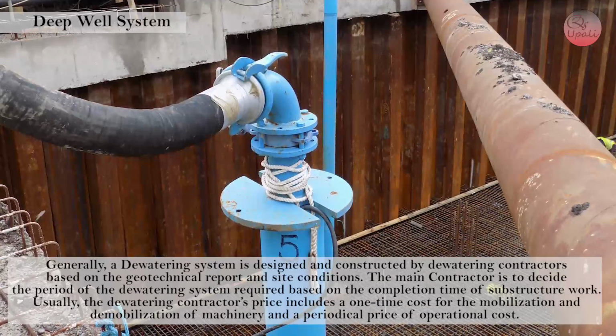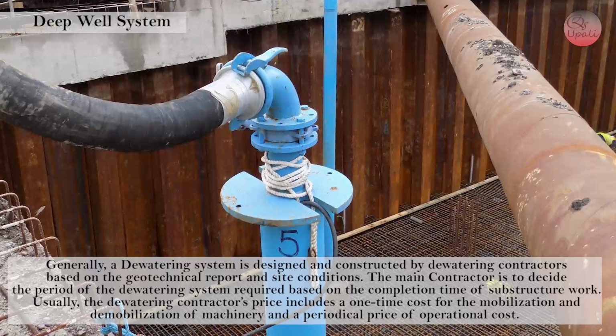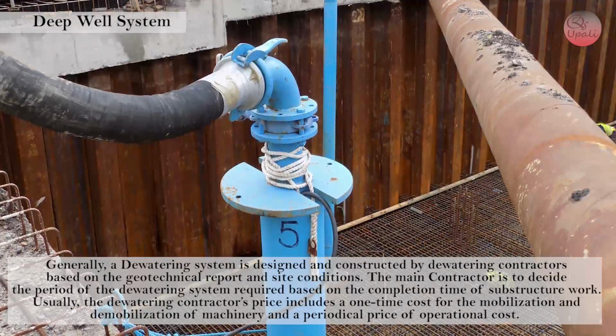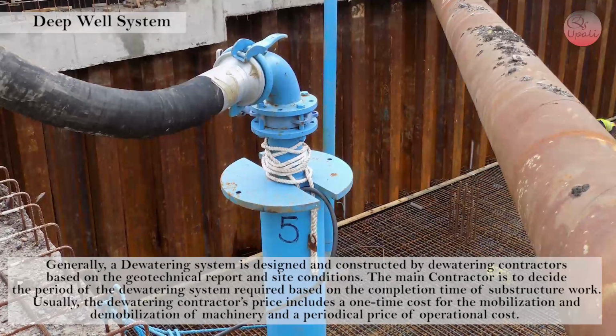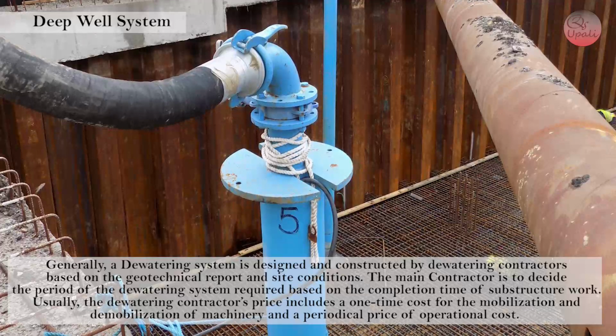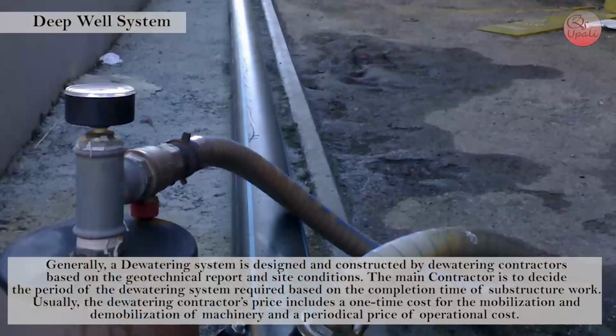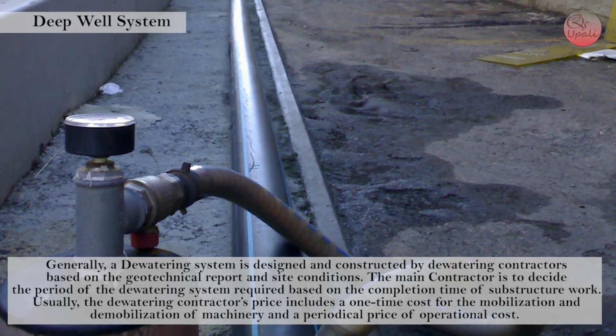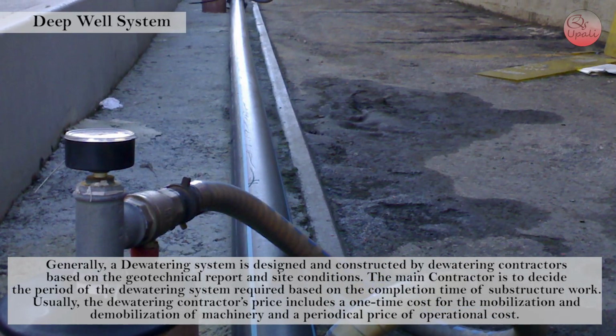Generally, the dewatering system is designed and constructed by dewatering contractors based on the geotechnical report and site conditions. The main contractor is to decide the period of the dewatering system required based on the completion time of substructure work.